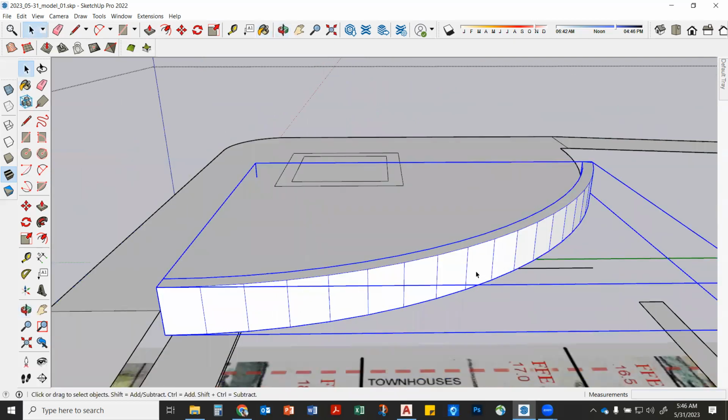I had a friend that would do all these models. He would keep everything on the 0 layer until he wanted to start doing materials. And then he would group all of his walls together, or all the walls with the same material. He'd put that all in one group so he could paint bucket. Boom, boom, boom, boom. And then if we were changing that, you just click it once and the whole thing changes, yeah?